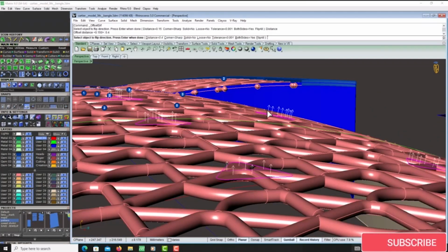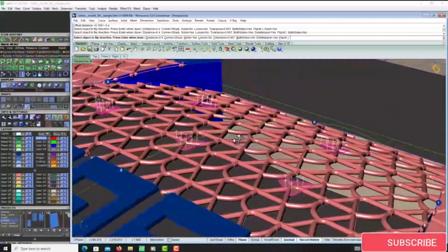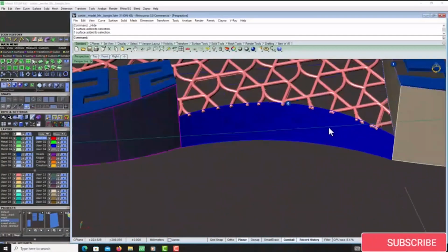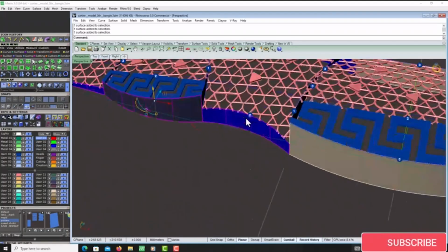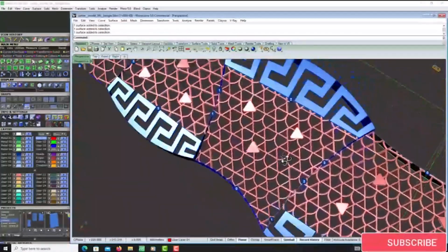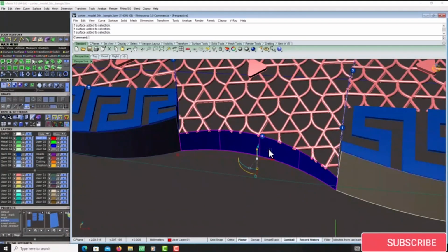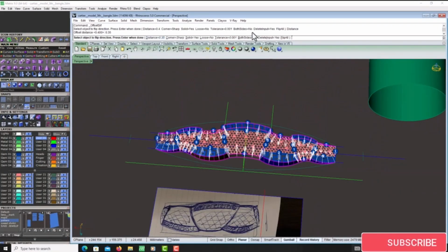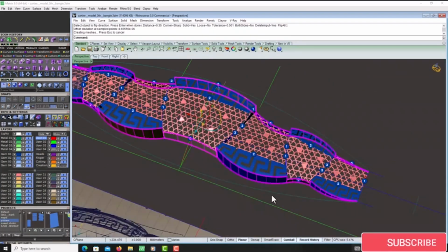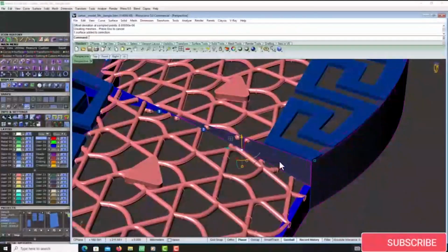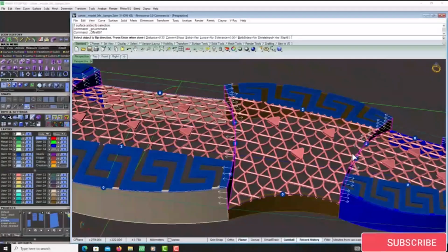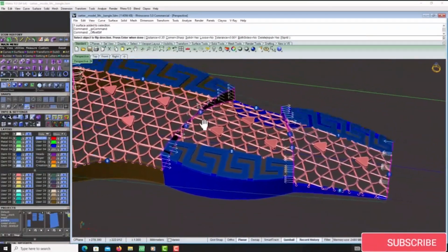Installing on a pattern and offsetting, just offsetting solid, distance is 0.4. Okay, we make these little surfaces, and then we are offsetting the walls of the bangle, offsetting it solid, yes, offsetting 0.35 millimeter this surface, yeah, and these surfaces, yeah, offsetting these surfaces too.